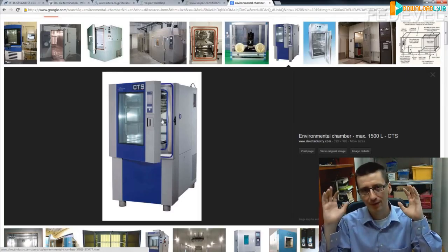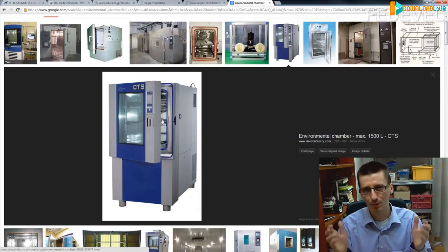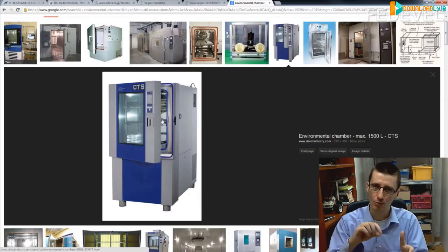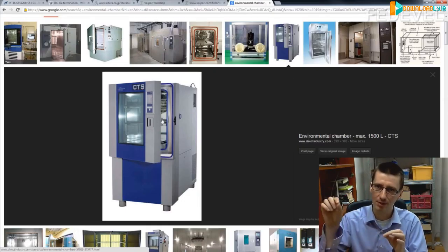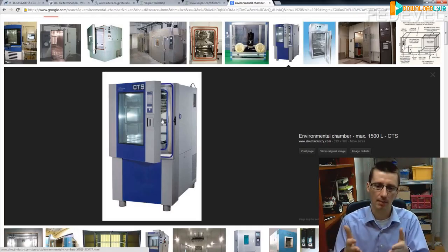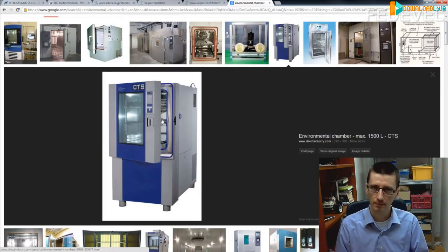There will be a mess. You have to clean it, and you should not open it at -40. So if your board failed at -40, doesn't want to start, you should set the new temperature, wait half an hour or 1 hour, and then open the chamber. It would take ages to debug your board in the chamber. It's not good. So always be sure it's running without error for a couple of days on your table.